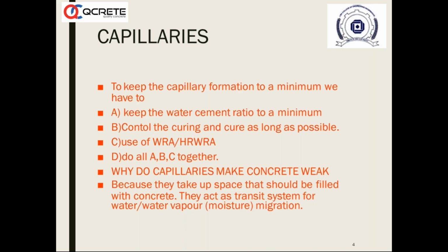So the capillaries take up space that should be filled with concrete. They act as a transit system for water vapor, moisture migration. They act as conduits. These capillaries act as conduits for transporting sulfates, chlorides, carbon dioxide, and all other materials affecting the durability of concrete.